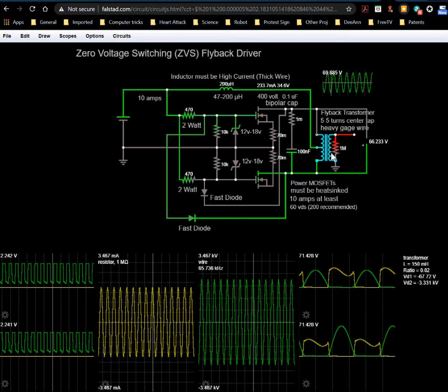But anyway, or certainly past the melting temperature for sure. But otherwise, this inductor and this capacitor is what sets the frequency here. So it really is just a tank circuit. It's 1 over 2 pi radical LC, the resonant frequency, so it's more or less in that ballpark. That's the frequency this will oscillate at, whatever your capacitance and whatever your inductance is. But since your inductance changes, it'll change.